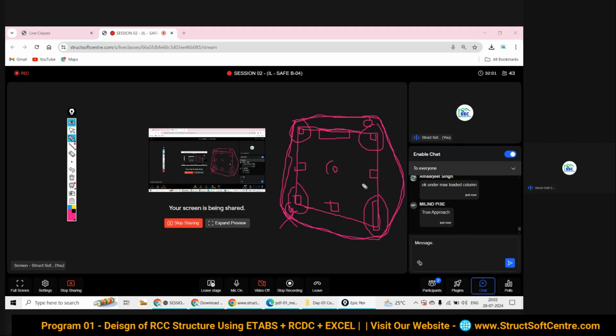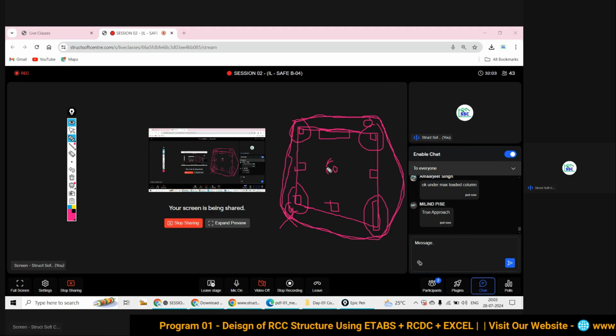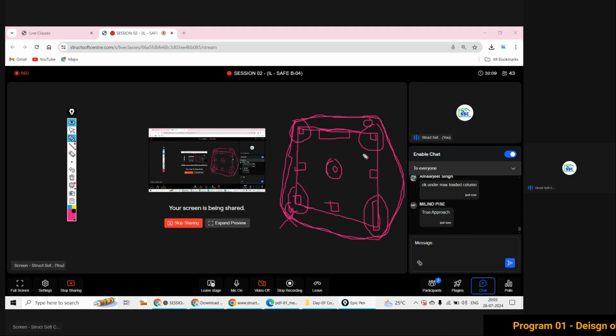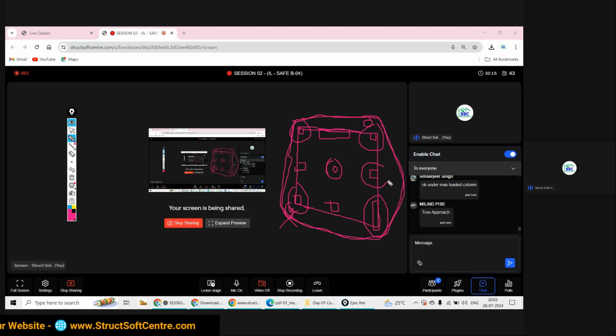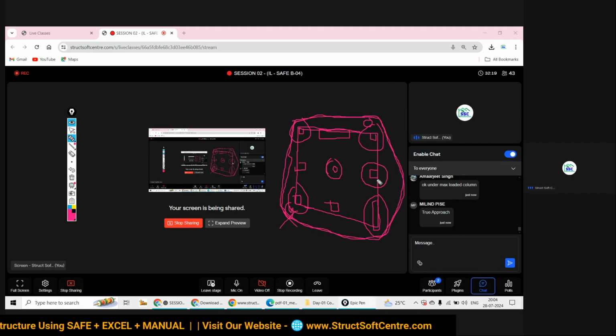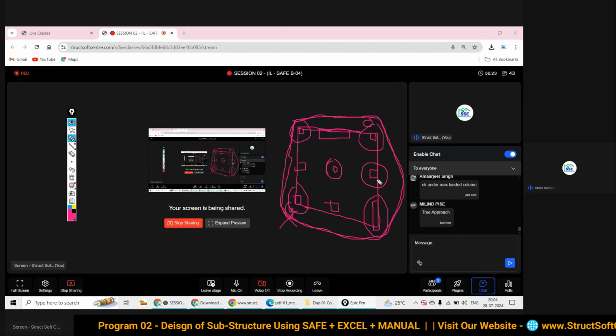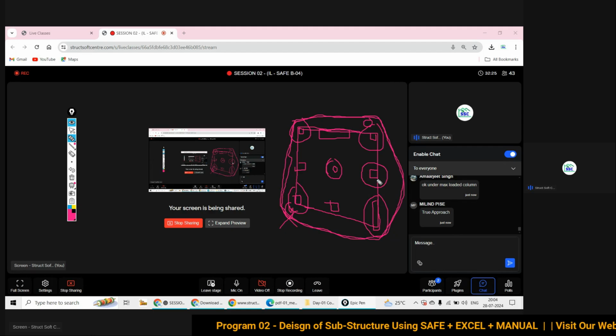But in addition to this, a sixth point is also going to be tested, because they want to know about the sixth point. At the sixth point they check where the maximum gravitational load or point load is coming. Suppose this is the point, so they choose this point for the sixth bore hole. Understood? So this is one approach in a critical situation. This practice is taken by practitioners. Understood?